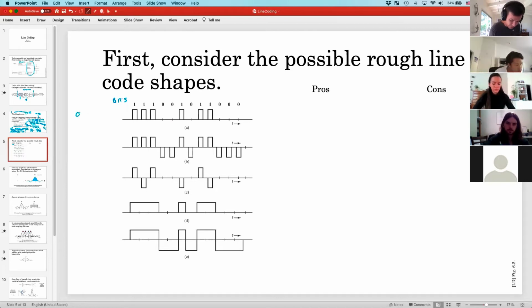I think you've seen this before. This is on-off keying, and this is in a return-to-0 sense. What we've got here is the bit period, which I think is consistent vertically. I borrowed this from the textbook. So if that's TB, then this is, say, tau less than TB.